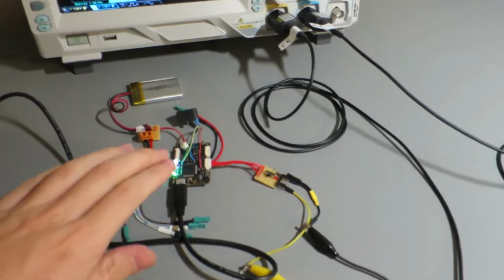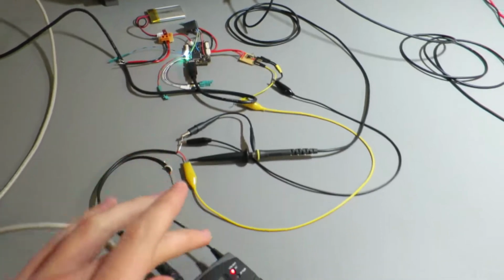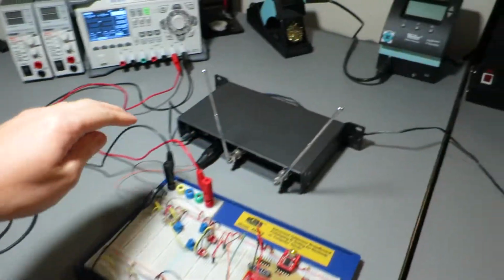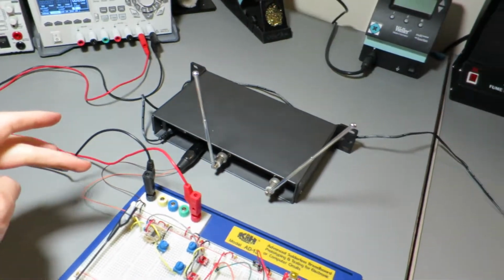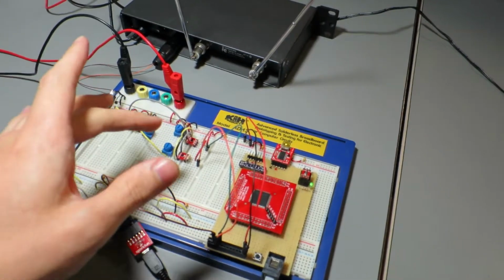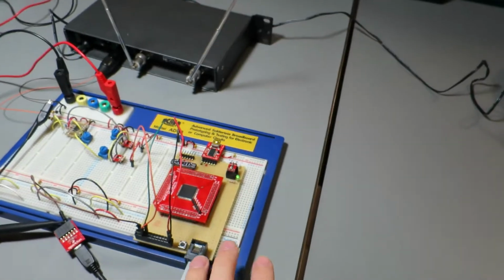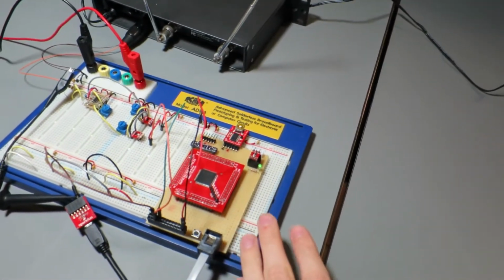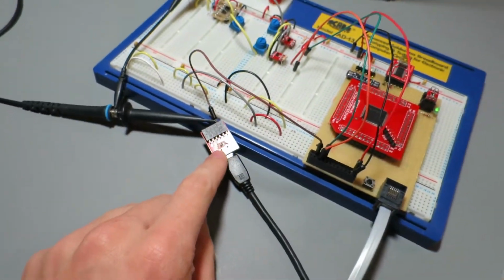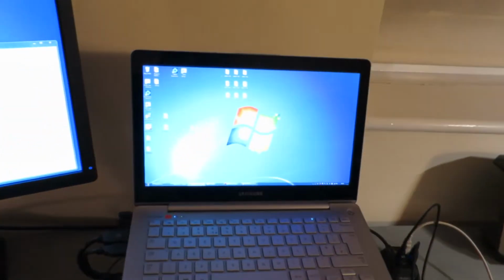So in this setup I have a sensor here which is streaming UART directly to the transmitter into its microphone input, and that's transmitting to this receiver. The audio signals coming out of the receiver into this circuit. There's a small analog front end here just cleaning up the signal a bit, and then a microcontroller just doing some logic to recover the UART signal, just going into this FTDI serial converter, and then that's connected by USB to the computer.